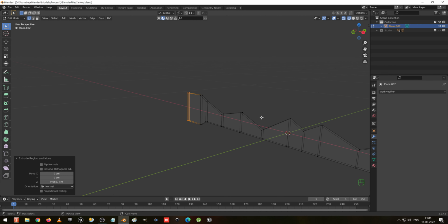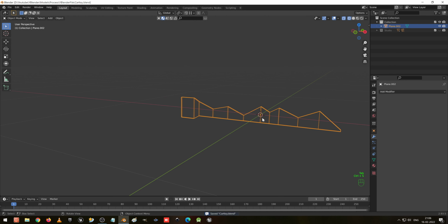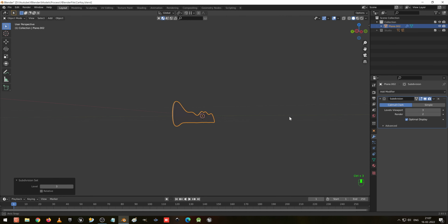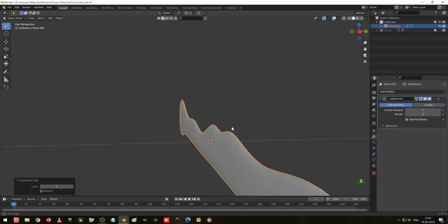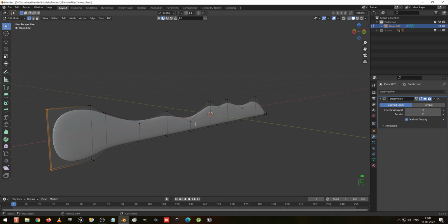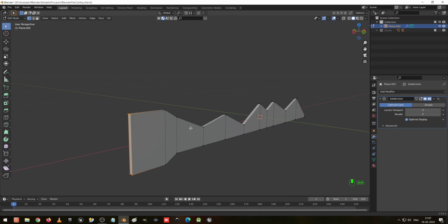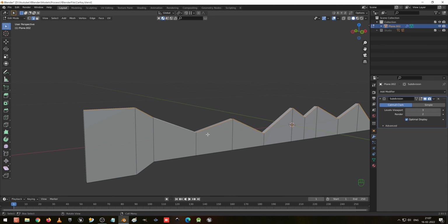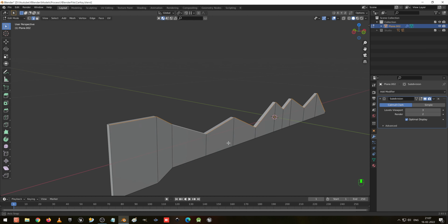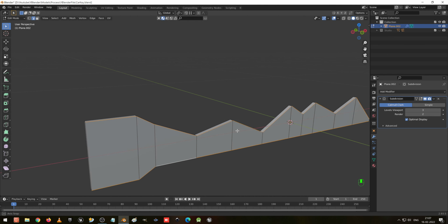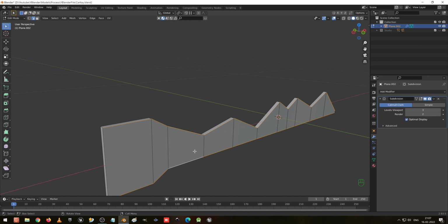So this is the key shape I have given. Press Ctrl 3 to apply a subdivision modifier, which looks like this, like a knife. We don't want this. I go to edit mode and turn off the subdivision in the editing tool. I am going to make sharp corners for these two edges, this one and this one, sorry, this bottom, which is required for us.